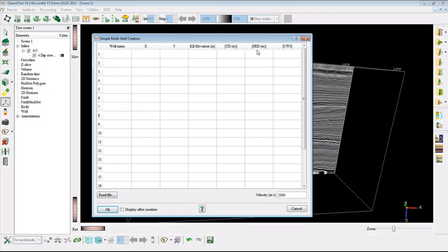But SRD and UWI, which are the seismic reference datum and unique well identifier, are not mandatory. You can add them or not. So really, those four or five columns you have to fill in. The good thing is that instead of importing one by one, with one file you have all your wells imported in one go.